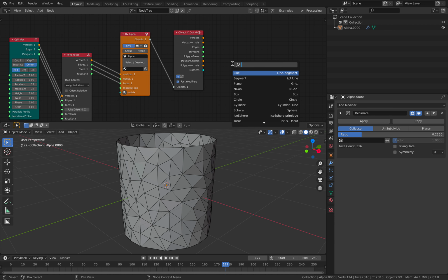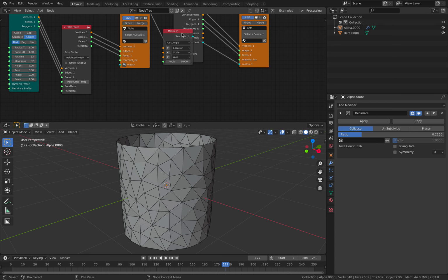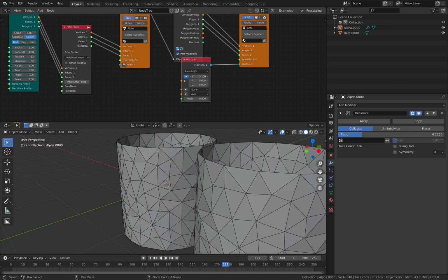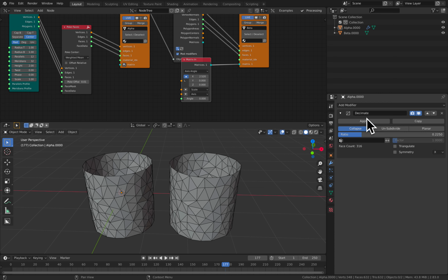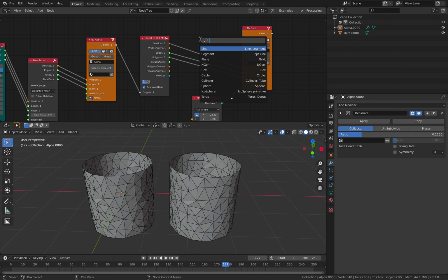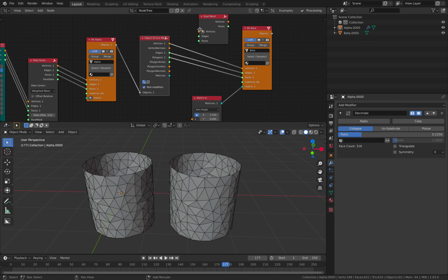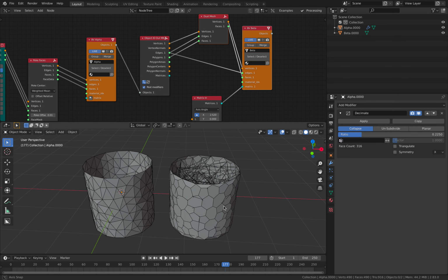All right. So now the next thing we want to do, let's create another B-mesh. Plug this in and just put it to the side. So this is our sphere chop process and also Decimate objects. The next thing we can do, because it's a triangle, with triangle and dual mesh, we're gonna get something that looks like a voronoi. So, fake voronoi.